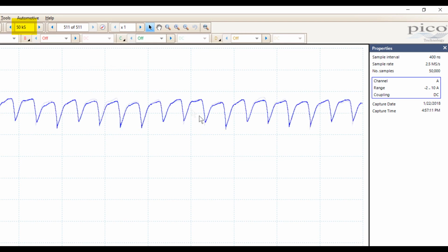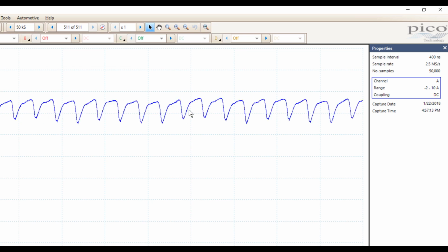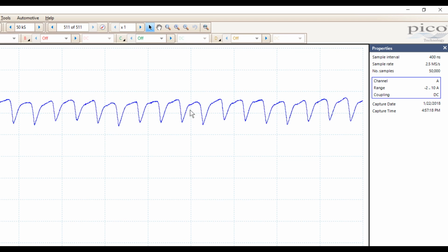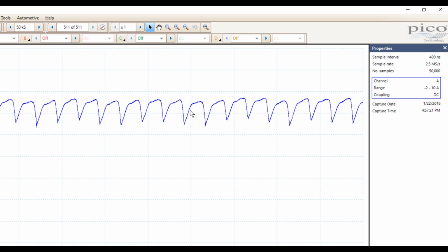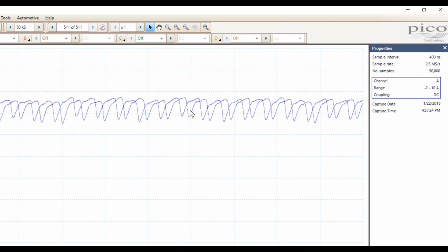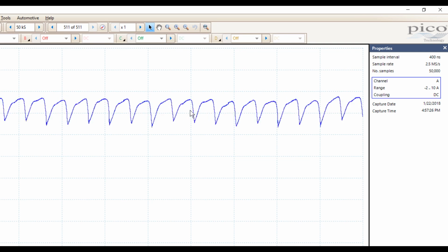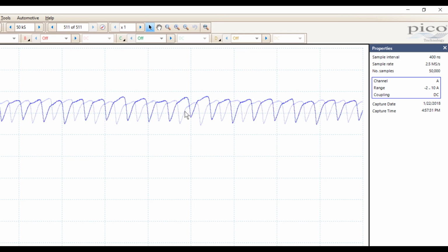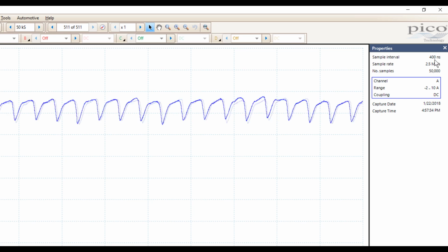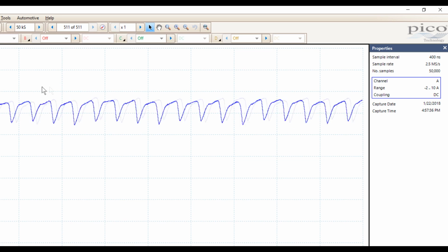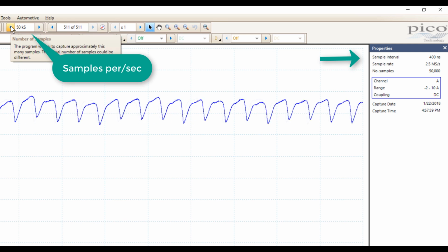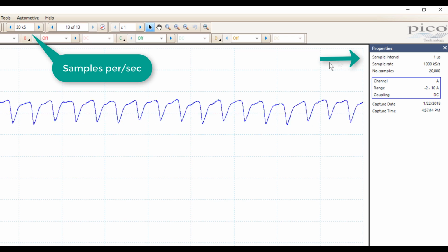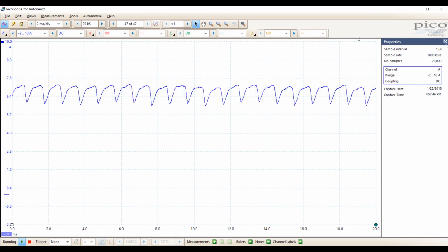If you're looking at ignition waveforms, you want to set that for 1 microsecond, because the whole entire duration of where the coil gets charged, the dwell period, the firing time, the burn line, you're only looking at 3 milliseconds. So you really want to sample every 1 microsecond. So I pretty much set my stuff for 1 microsecond. So I'm going to turn down the sample rate, and if you look, you can see the sample interval is now at 1 microsecond. So now that's what I have.